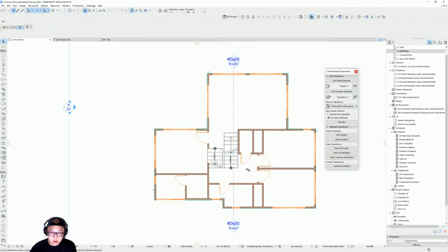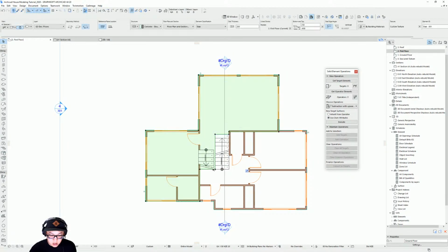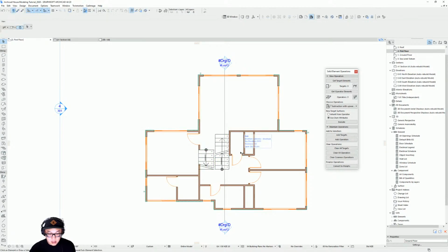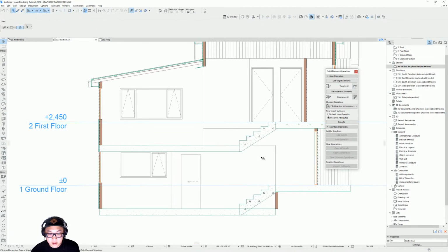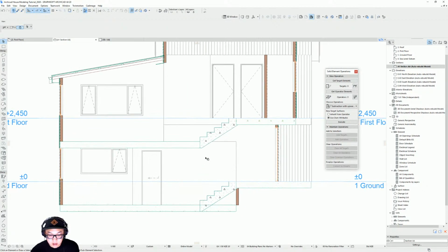I'm gonna go into the upper levels, and this needs to be shifted. This one. I'm gonna make a copy. So now I'm gonna have the same staircase at that level, and if I take that section line and I can drag it, so Control D, line up to here, open the settings, and you can see now I have the room height 2 meters.